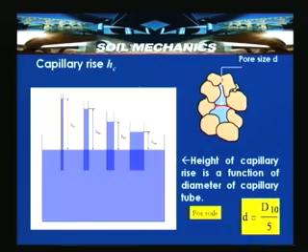So, for soils, the pore space is approximated as 20% of the effective particle size. The effective particle size we have discussed and introduced earlier is D10, which means that 90% of the particles are larger than this size and only 10% of the particles are finer. So, 1/5 of the D10 particle size is referred to as the pore space.